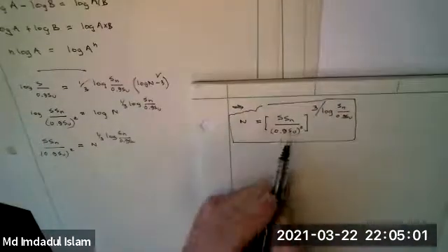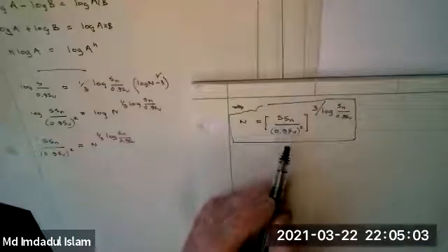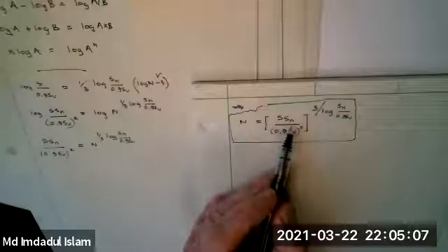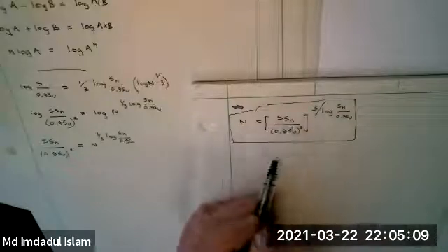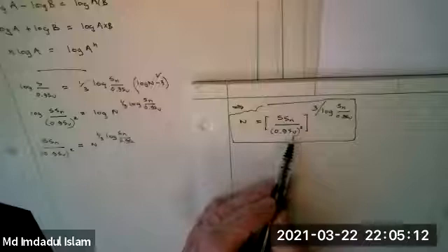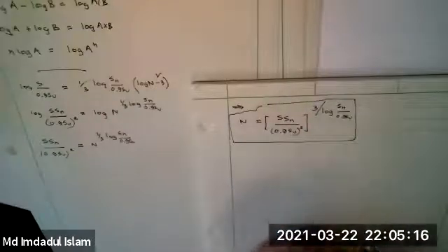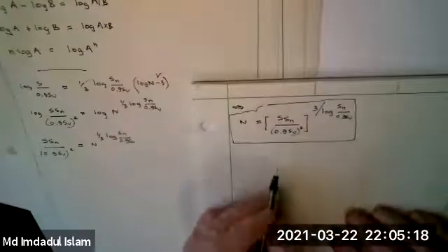So if you give me a bending moment and I get the stress, if I've got the endurance limit measured from some other test and the ultimate strength measured from some other test, then I can tell you the life. We can simplify this.